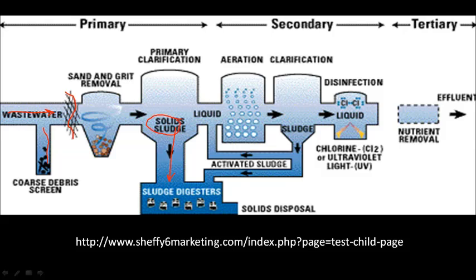We also have the secondary treatment phase. Okay, so this is using the activated sludge method, where we have aerobic metabolism occurring in the activated sludge tanks. Okay, secondary clarification, where the sludge accumulates, and that can either be collected and sent to the sludge digester, or it can be recycled to re-inoculate the incoming primary effluent into the activated sludge aeration tanks. And then we have the disinfection stage. So in this case, they're using chlorination, although you might use ultraviolet light, or they might use ozone.